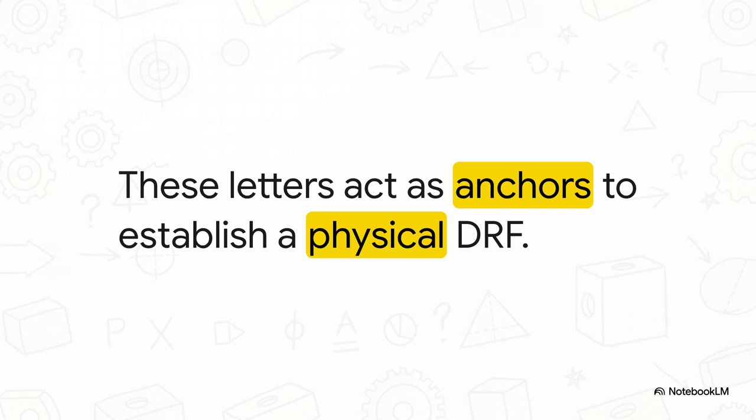All right, step 3. Finally, we read the right side of our sentence, the datum references. You can have primary, secondary, and tertiary datums. Think of these letters as anchors. They lock our 0.25 cylindrical tolerance zone into a physical datum reference frame, a strict coordinate system established by actual physical features on the part. Without them, our tolerance zone is just kind of floating aimlessly in space.